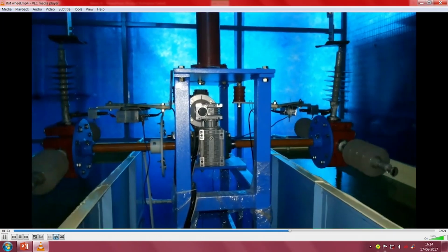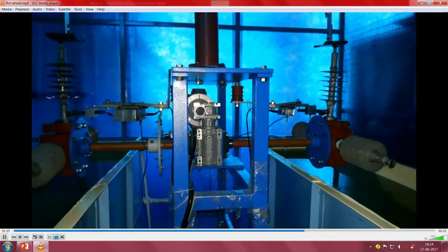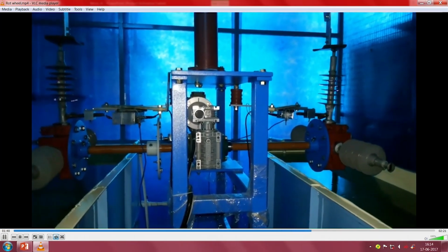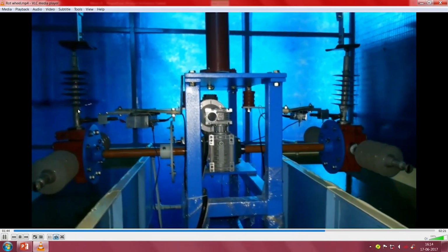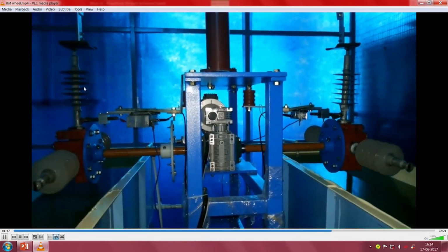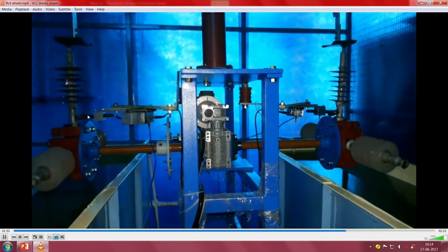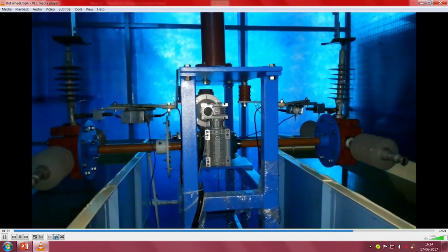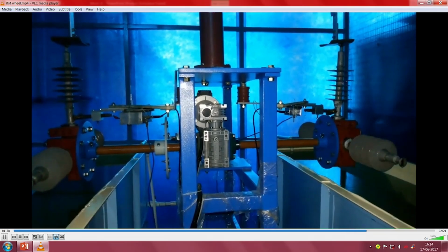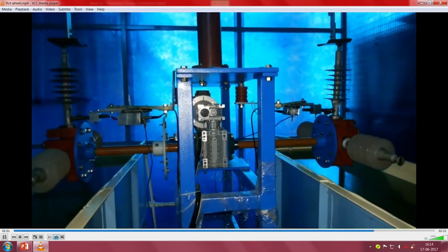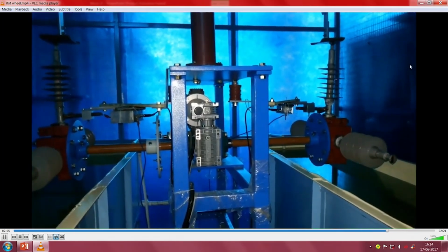You can see how the experiment is being carried out. Initially, due to wetness, you can see several discharges because of the wet surface. Later on, because of the stress, there will be drying up, and suddenly you see the discharges or the conductivity coming down; the leakage current flowing on the surface also comes down. So, this is how the experimentation, a very important experimentation for the evaluation of polymer insulators, is done.